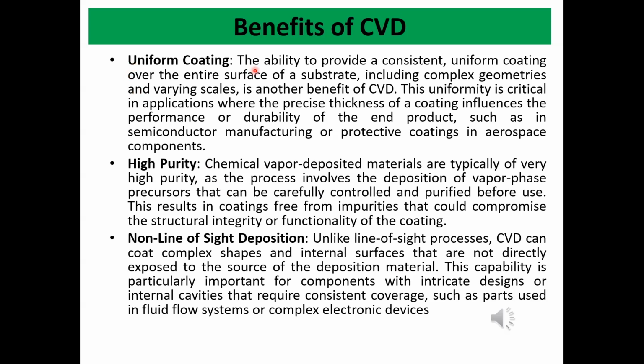Uniform coating. The ability to provide a consistent uniform coating over the entire surface of a substrate, including complex geometries and varying scales, is another benefit of CVD. So using CVD, we can put uniform coatings on those objects which have very complex geometries.